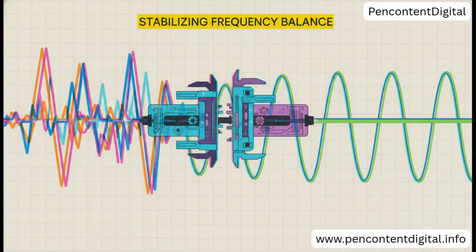And to actually survive those massive hits we just talked about, engineers rely on dynamic simulation. This guarantees the grid keeps its delicate synchronism. If a sudden shock causes a huge frequency drop, the network might just trip completely offline. So dynamic simulation tracks transient stability and frequency response over time. It lets engineers design automated controls that catch and stabilize the grid right before things cascade into total chaos.